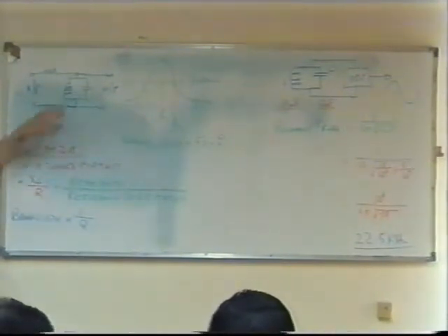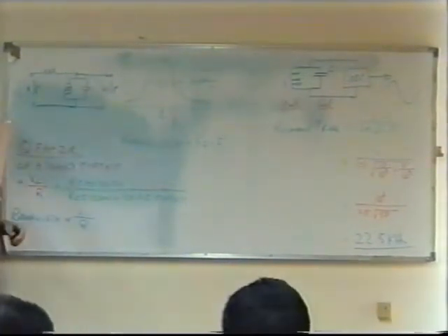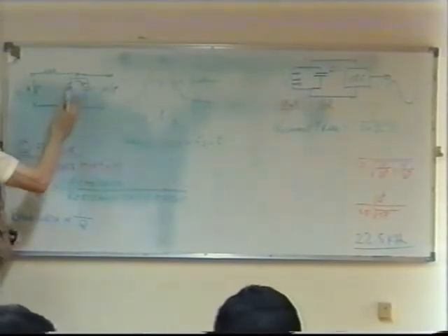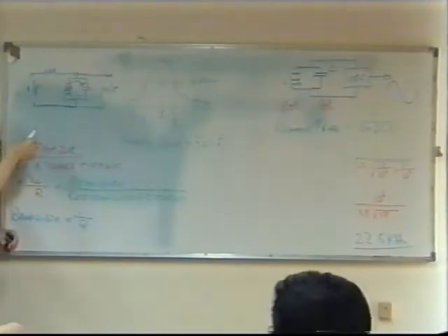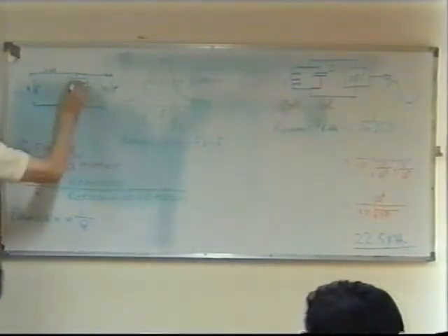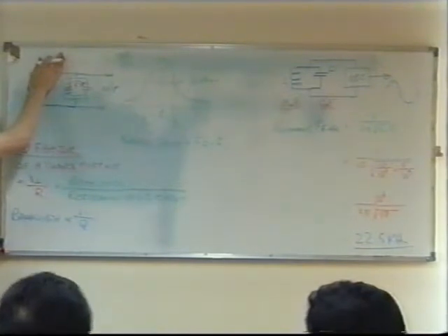R is the resistance of this circuit here that I didn't mention yesterday. It's the resistance of this circuit, because of the windings of the coil, perhaps, and the connections and losses from the circuit, perhaps through radiation or whatever, that introduces a certain value of resistance in the circuit. And it's this R that we're using here, not this. That's part of a filter.